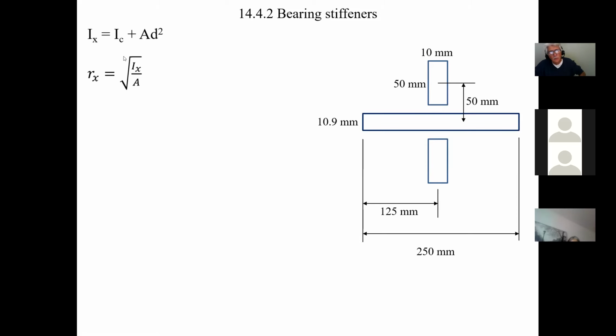Okay. In other words, if you're not sure, you should do both and take the smaller. I calculated the moment of inertia with this because this is the base. I mean, this is the height, and you know that it's 1/12 the base times the height cubed.